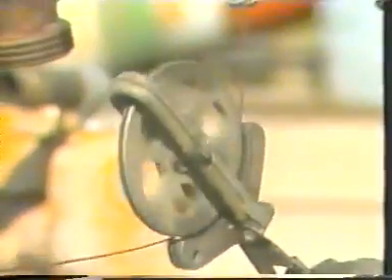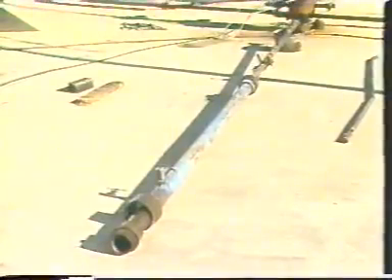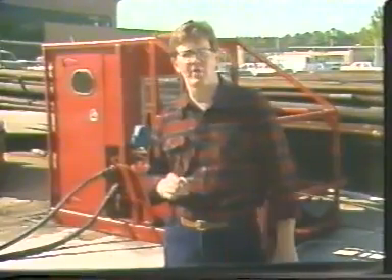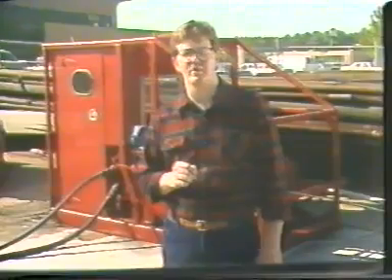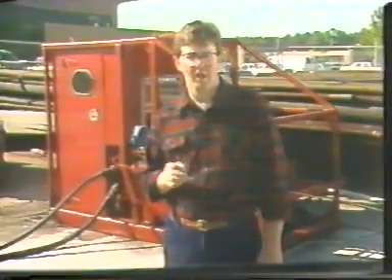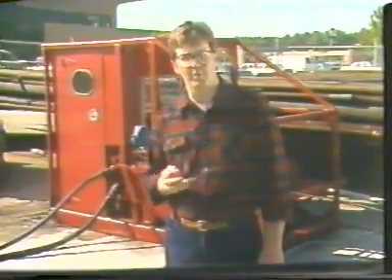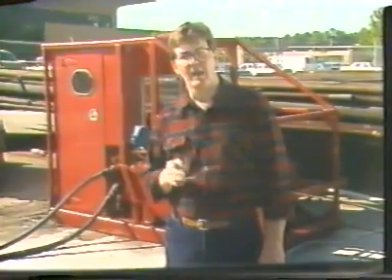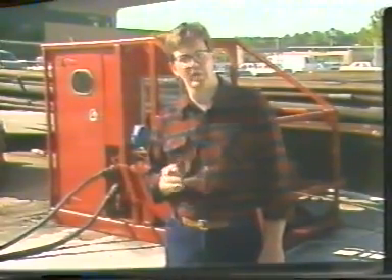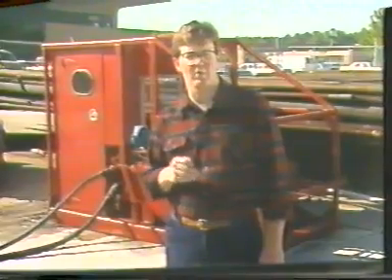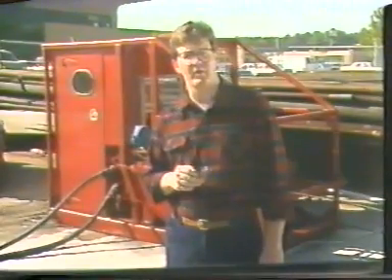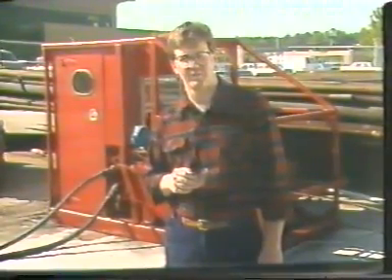It's fairly straightforward. A steel wireline, of course, a system for bringing it to and out of the well, and the appropriate assembly of piping and connections to permit pressure to enter from the tubing. Also required are a device for accurately measuring the length of wireline in the well, another device to measure the force being pulled by the wireline, and a series of tools which can be easily and quickly attached to the end of the wireline to perform the necessary subsurface activities.